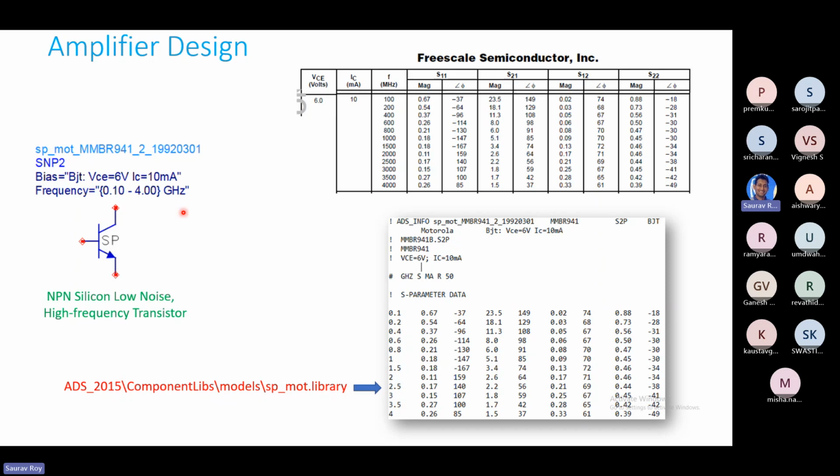This is a linear model because the S parameters are a linear model, and you get it for a particular biasing only. Another possibility, the better option, is a nonlinear model. If for a transistor you have all the internal parameters given, then you can do all this analysis in ADS itself. For defined bias conditions, you can do a DC analysis and find out the S parameters.